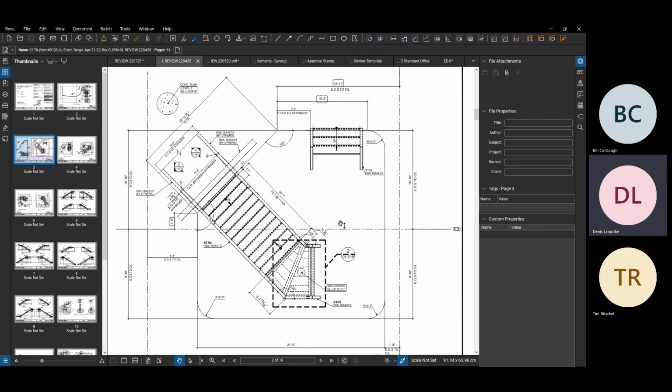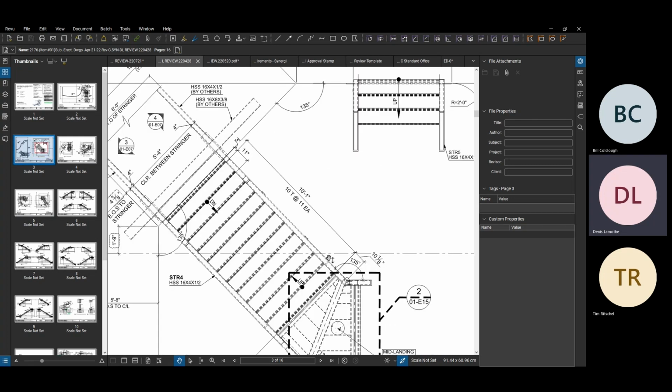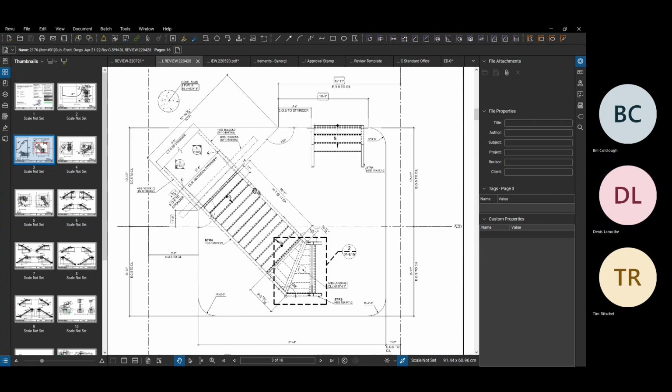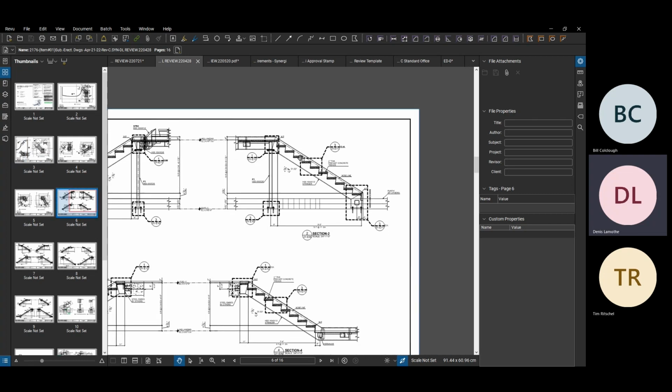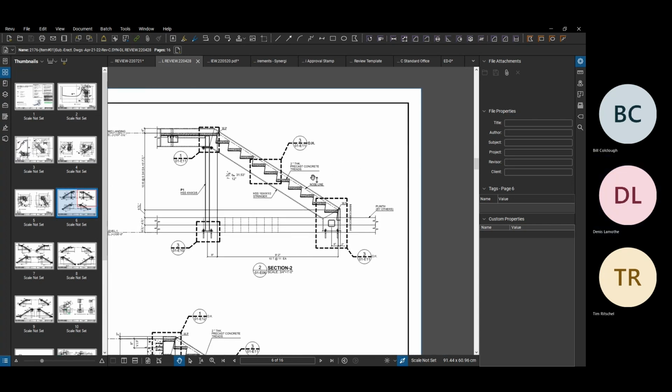But it's one thing that we need to just keep an eye out for, is to make sure that when we model or design something, sometimes we see 10 treads, but for whatever reason, we may model 11 or 9. Or on the architectural set, there may be a tread that's flush with the top of the floor. So it's something that might be inset in a concrete slab, for example. And on the architectural drawings, they'll actually count that as a tread. That could throw people off when they're modeling. So just check with the stair sections to make sure that we have the right number of risers and treads to match the original design.